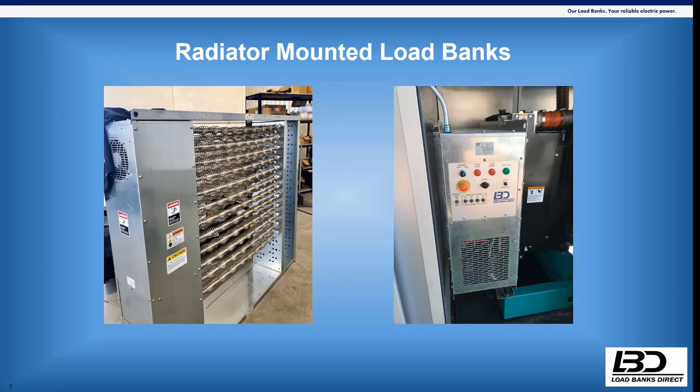You might ask yourself, why is LBD recommending that it be 30 to 50% of the generator capacity? It's because you can't break any laws of physics here. The radiator cooling fans on engines are designed to take the heat off the engine, that's what they are there for. So we capture that airflow. When we ask what the core dimensions of the radiator are, we typically need that information at time of order, and we make our opening for the resistor frame, like Eric was saying, the same size as that. We mount the resistors in there. We capture that airflow coming off there.